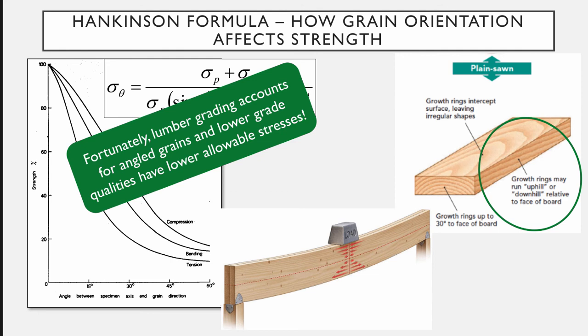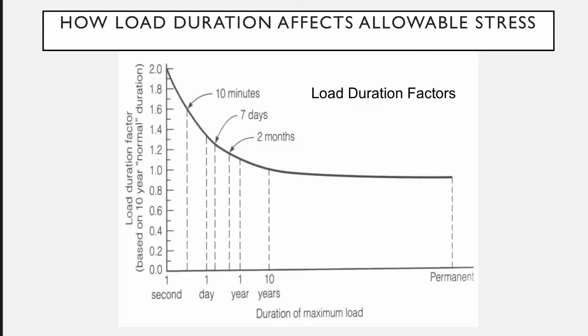Another thing that also affects, and we mentioned in our first video, how much allowable stress we can put on the board is our load duration. In fact, with timber, you have to multiply whatever the grade's allowable stress is by a lot of factors. Some of it is how much moisture. Is it going to be exposed to moisture? Boom, reduce the capacity. Do you have a lot of boards, a repetitive use member? We see redundancy is great. You can actually increase your strength.